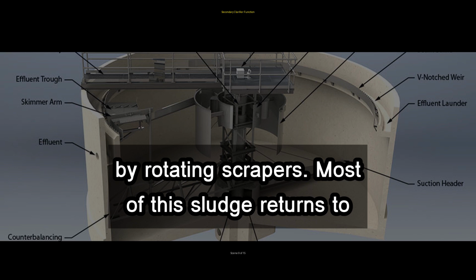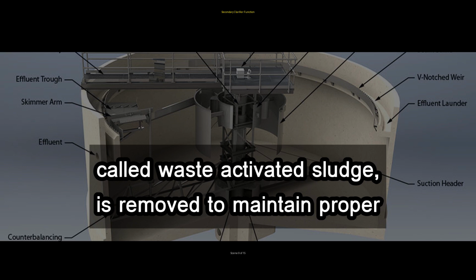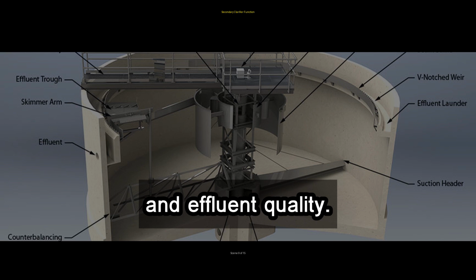Most of this sludge returns to the aeration tank as return-activated sludge. Excess sludge, called waste-activated sludge, is removed to maintain proper MLSS concentrations. Clarifier performance directly affects overall treatment efficiency and effluent quality.